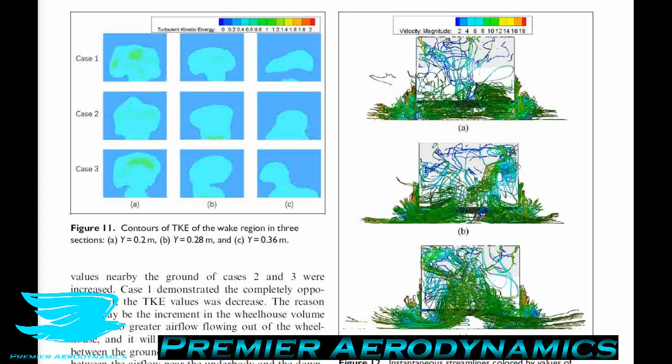On the other hand, when you put the Mercedes wheelhouses on the Ahmed body, the flow in the wake pops up to about halfway up the vehicle. You can see the flow coming around underneath, and it just jumps straight up to about where the back of the trunk would be, the back of the boot before the windshield. So that indicates, just from this, that the wheelhouses from the Mercedes car would produce more downforce than the other two. But again, this is instantaneous, not average, so we need to take that conclusion tentatively.